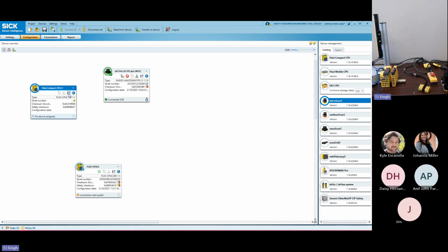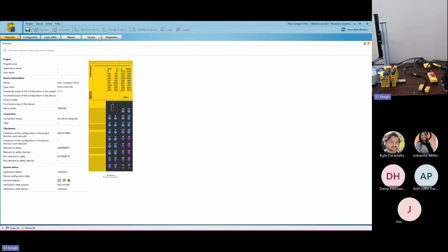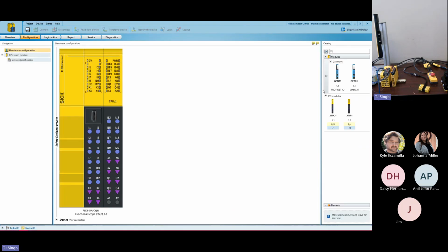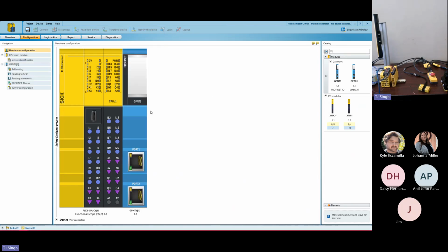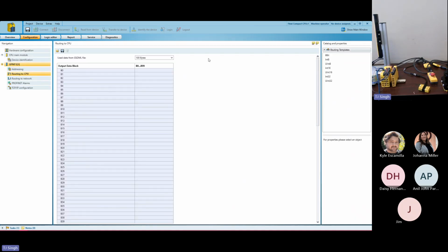The next thing is probably having something like a Flexi Compact. I don't know if you guys have ever used this one. If you have a nanoScan, you can take one of the outputs and use this Profinet gateway here, and just route the information from that scanner to one of the bits, and get that information on any of the bits, that hey, that triggered.